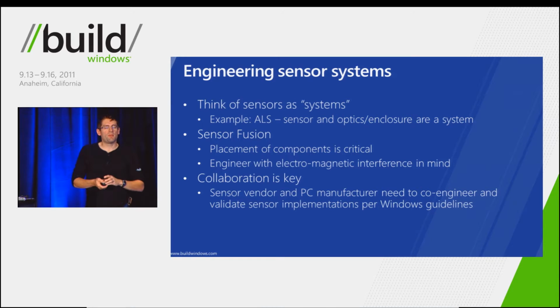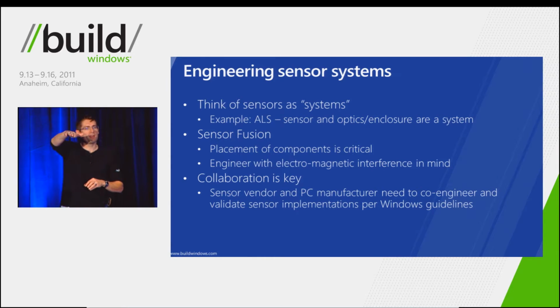So in some cases, you might have as little as, say, 50% light transmittance. Well, if we have 100,000 lux, which is a typical outdoor ambient lighting condition, and we have 50% light transmittance, that means that we only have 50,000 lux getting to the sensor. So the actual dynamic range of our sensor is more like 2 lux to 100,000 lux, which is actually good news because that's what we really want. We require at least 30,000 lux because we want to be able to detect outdoor lighting conditions. But if you can go up to 100,000 lux, then you can support a wider variety of different environmental conditions.